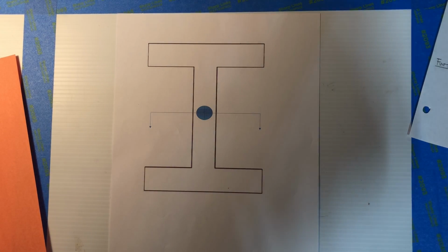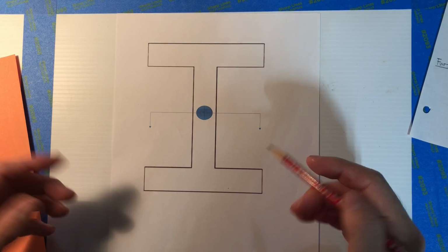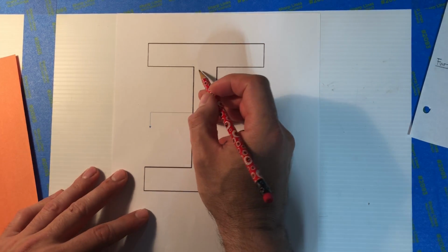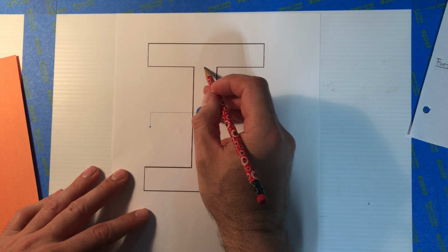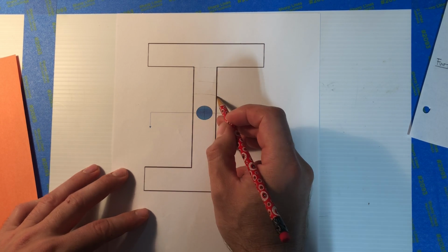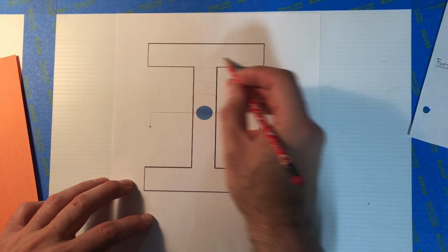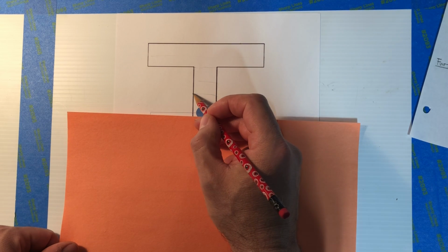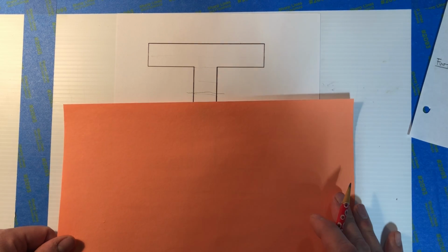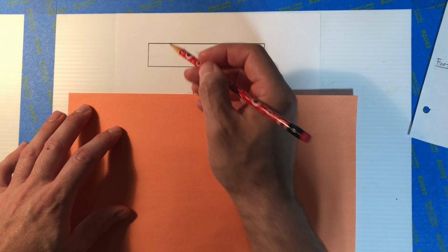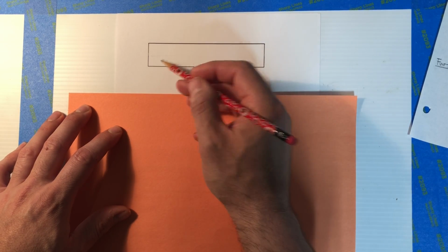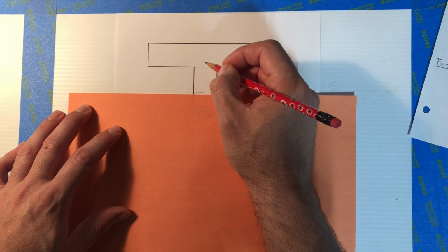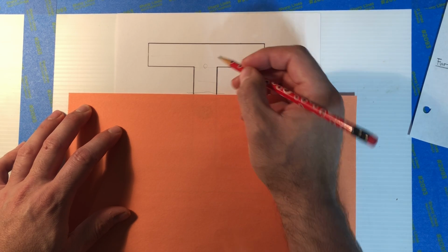Shear stress is zero away from the beam and maximum at the neutral axis. So if I wanted to find the maximum shear stress in this cross section, I naturally would want to find it along the centroidal axis. But what if I wanted to find the shear stress here, or here, or here, right? Basically, wherever you want to find the shear stress. If I wanted to find the shear stress right through here, it would be just like blotting all the rest out. Now this is my area that's left, this two-piece area. Where is the centroid of this whole area? It's probably somewhere over here, right?